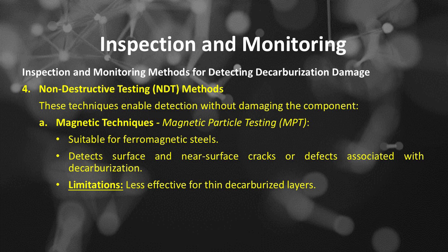Number A, magnetic techniques, magnetic particle testing or MPT, suitable for ferromagnetic steels, detects surface and near-surface cracks or defects associated with decarburization. Limitations: less effective for thin decarburized layers.